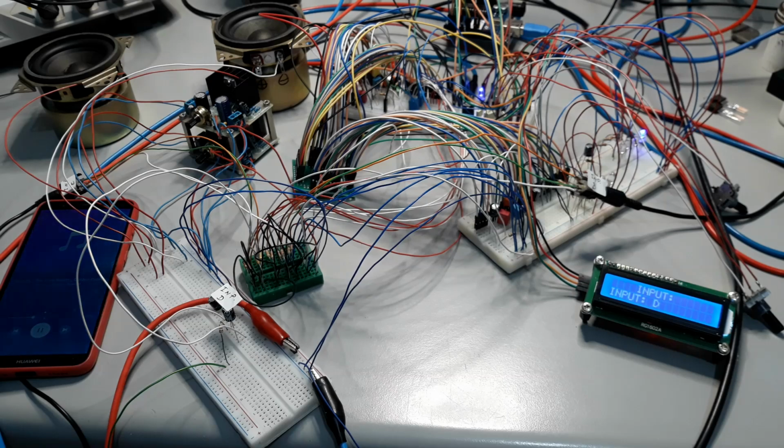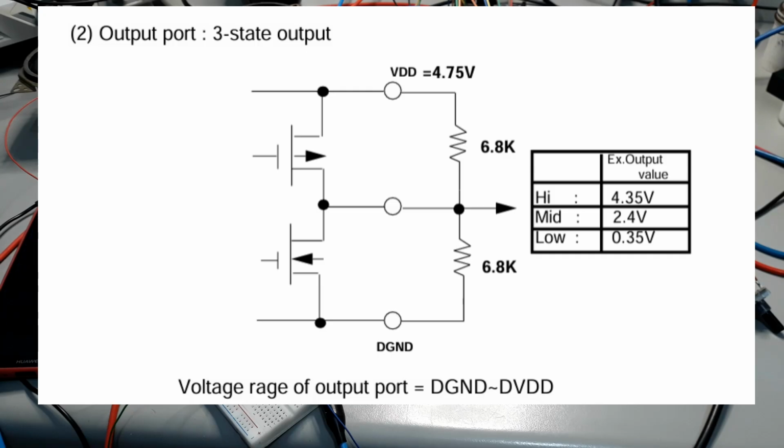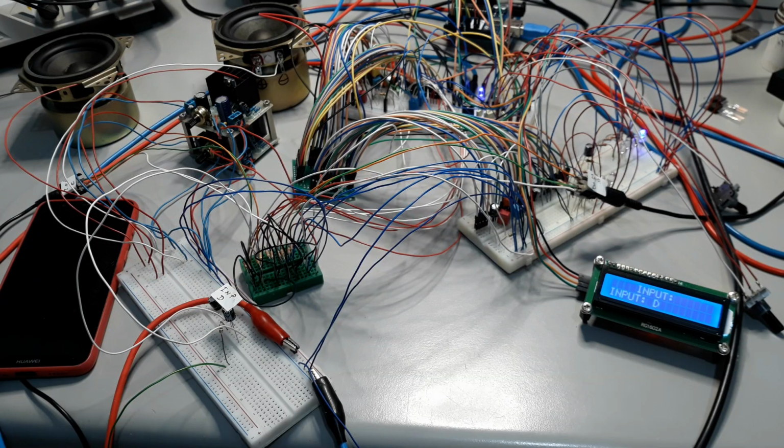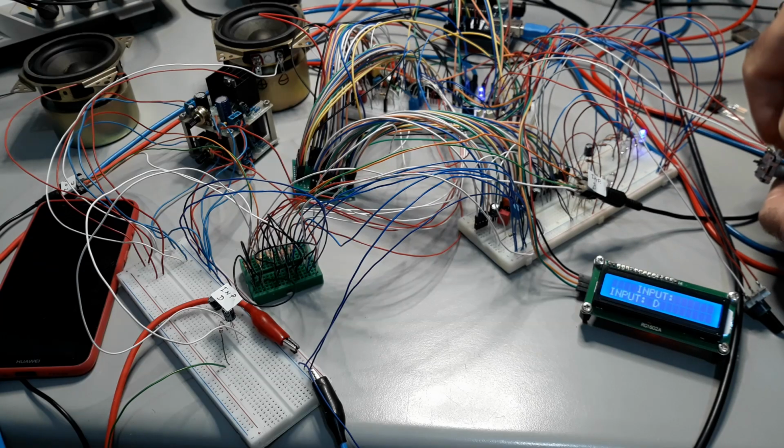There is also an additional group of 2 outputs that supports 3 different status signals. Because there are 2 groups of 4 outputs, we decided to configure the first group to count from 0 up to 15 using hexadecimal representation.